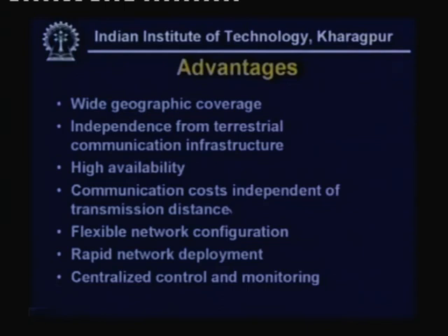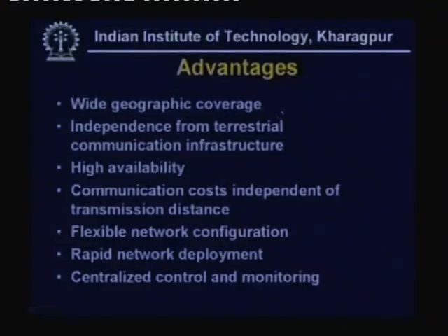Now, what are the advantages of this satellite communication? One advantage is wide geographic area, as I have mentioned. You can cover a very large area. For example, with the help of 3 satellites, you can cover the entire globe. Another very important advantage is independence from terrestrial communication infrastructure. Whenever you want to have wired infrastructure, you have to first lay the cable.